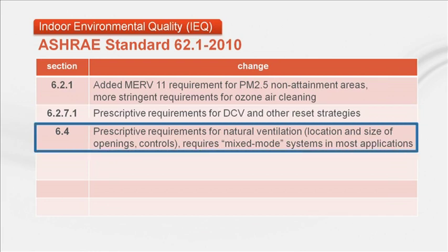Next, prescriptive requirements have been added for natural ventilation. These focus on the required location and size of the openings versus the floor area to be ventilated, as well as controls needed to coordinate operation of the natural and mechanical ventilation systems.